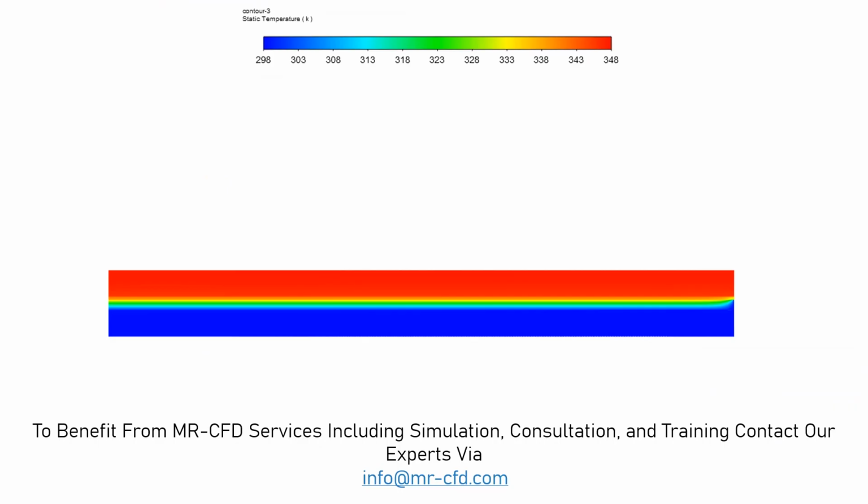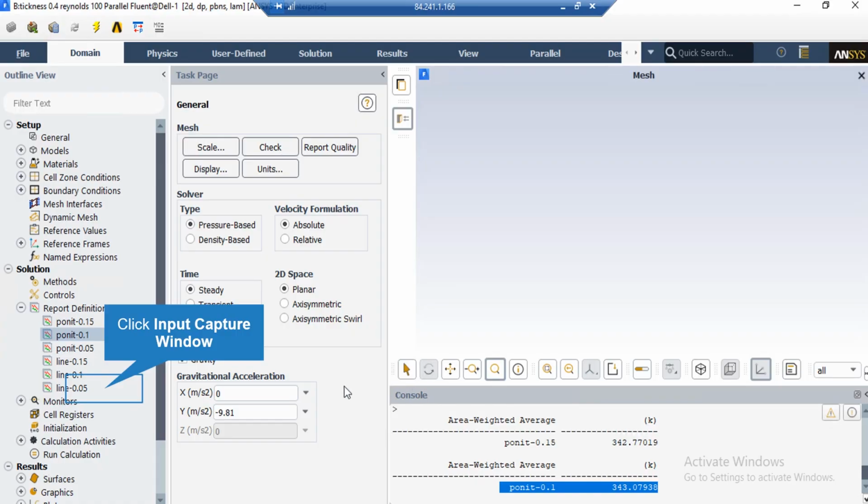Now in this contour, you can easily see the temperature distribution inside our computational domain. As was expected, the upper part, which contains the hot saline water, has a higher temperature in comparison with the pure water flowing in the lower channel of the geometry. It should only be mentioned that point reports give you the temperature on the membrane boundary, whereas the line reports give you the temperature in the bulk.